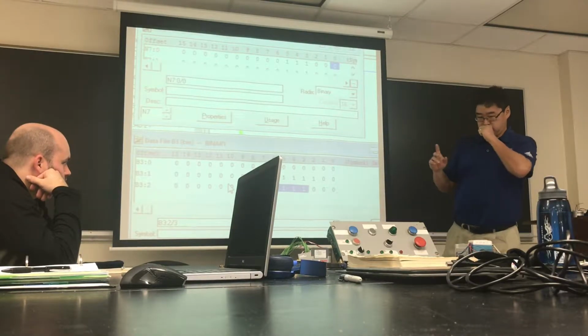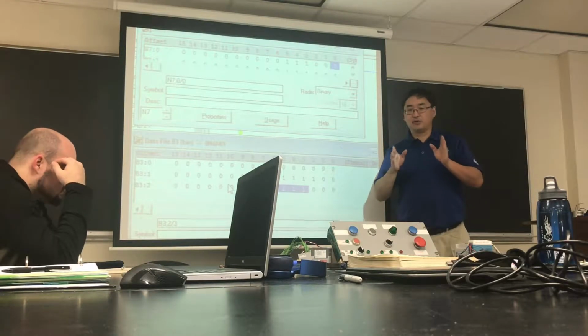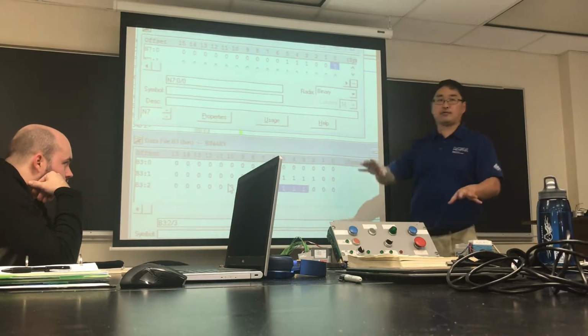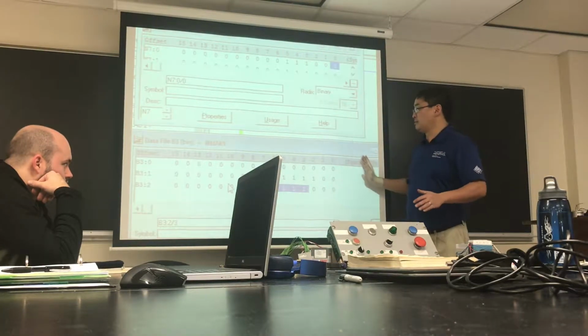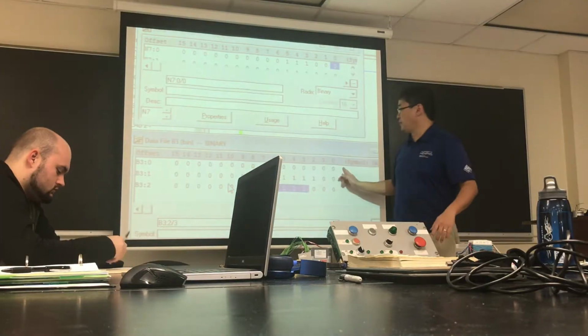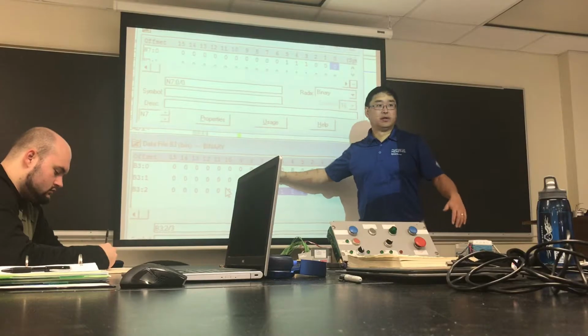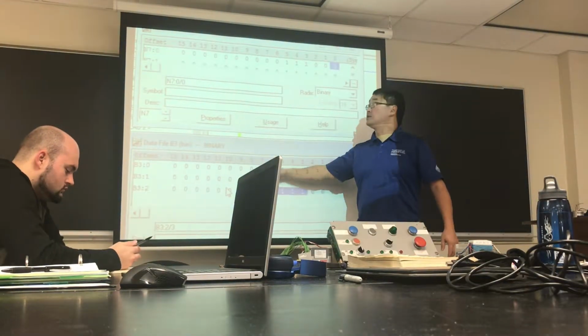So you have to plan ahead a little bit, and as long as all your inputs on your PLC, whatever card they're in, start at 0 and work their way up from least significant to most significant. And so maybe I only have 4 bits or I have 8 bits, doesn't matter. As long as the least significant is here, the most significant is there input-wise.